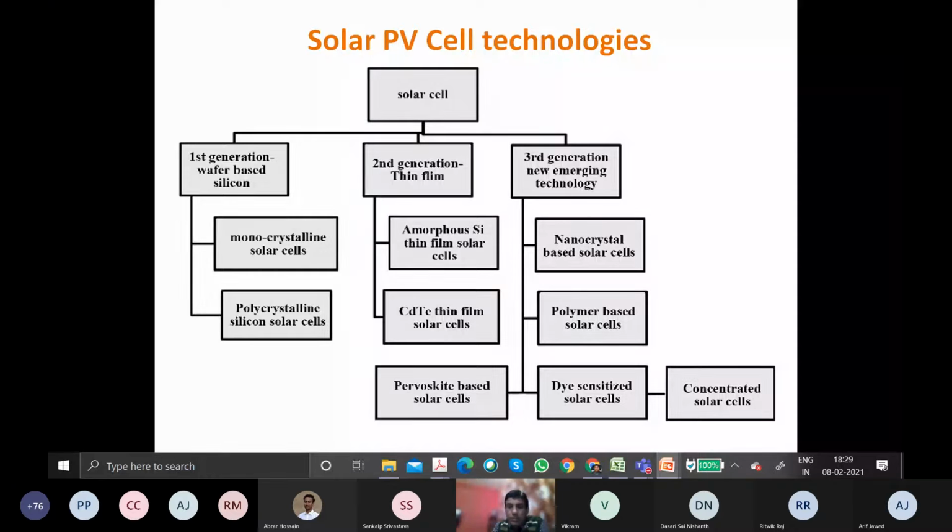So whoever is manufacturing solar modules in India, they are importing the wafer, or they are importing the cell directly. Then those cells are fitted, and the module is manufactured. So all these cells are series connected, and they are encapsulated within the glass and substrate, and the metal framing is made. So basically the module is made. And if they import the wafer, then the processing on the wafer is made to make it a cell. So there are 4 or 5 stages from which the wafer is converted to a cell. If you see a wafer, it will be gray in color.